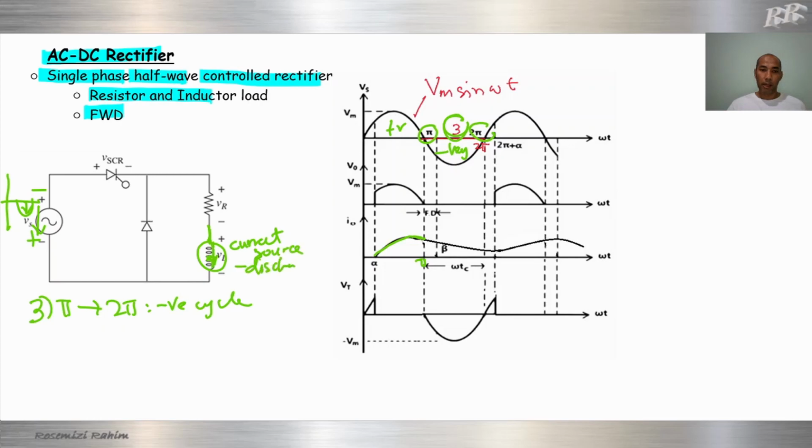It will discharge energy here. This one is the V source, and this one is the current from the inductor. It will go here, then the current goes here. The arrow of the diode and the arrow of the current are the same direction, so that means this diode will be switched on, forward biased.